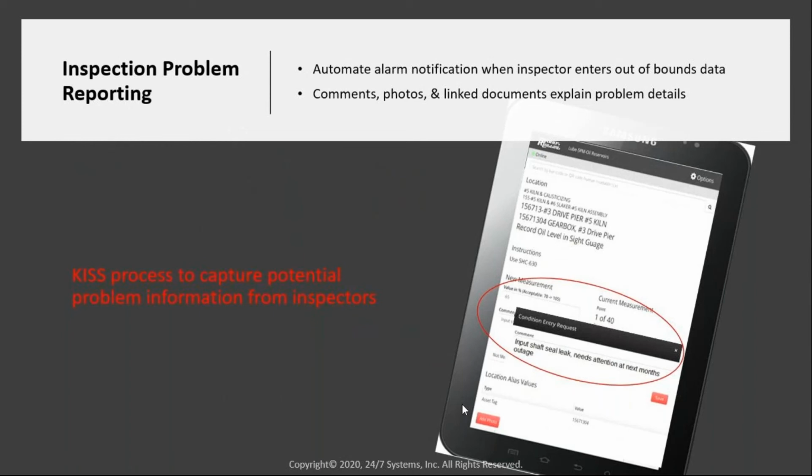Because I'm going to be able to take this information from the technician, the operator that's doing this walk-around inspection, and escalate it up through a process in the cloud database so that it gets integrated with findings that are coming on a particular motor or a particular gearbox. And the findings that are coming from the walk-around inspection are going to end up right there alongside any potential problems that are being reported by those more sophisticated technologies like vibration and thermography.